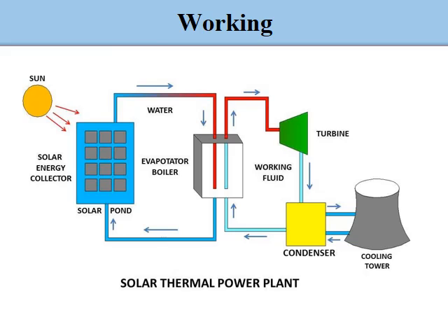Sometimes the working fluids gain energy directly from the sunlight, or sometimes through the solar pond. As the solar radiation strikes the surface of the solar collectors, the working fluid gains heat, its temperature increases, and it flows in the tube.